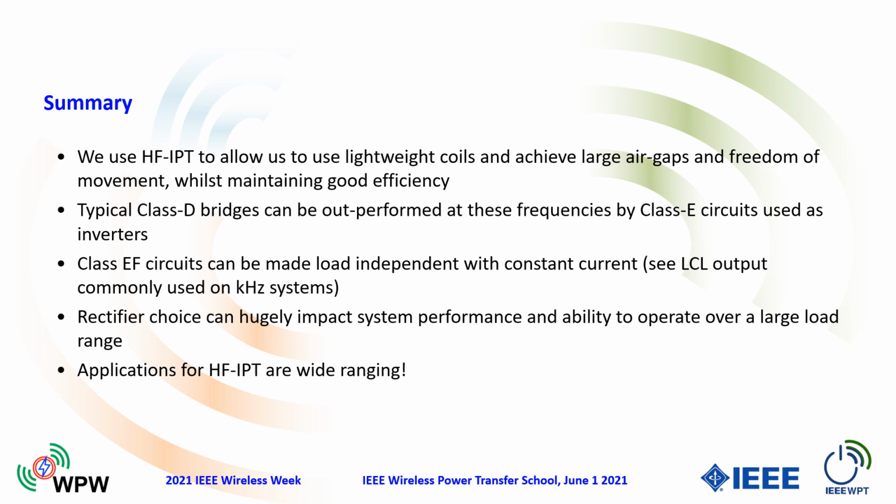Rectifier choice, of course, is important. I didn't have very much time to talk about rectifiers, other than to say we favor the use of resonant type topologies again with the rectifiers, so that the parasitic capacitances of the diodes do not detune our systems as we change our throughput level. And the applications for high frequency IPT are wide ranging, and I think they're quite exciting.